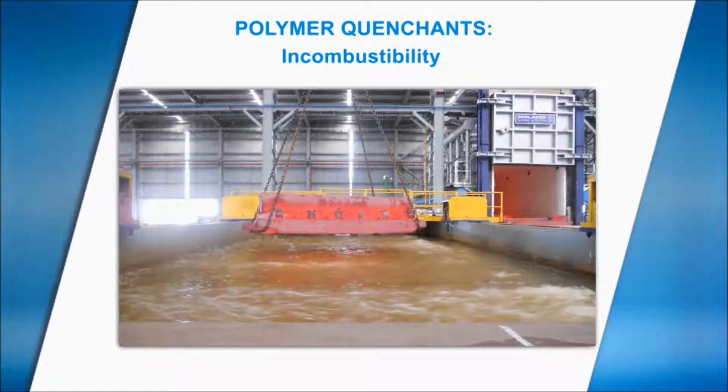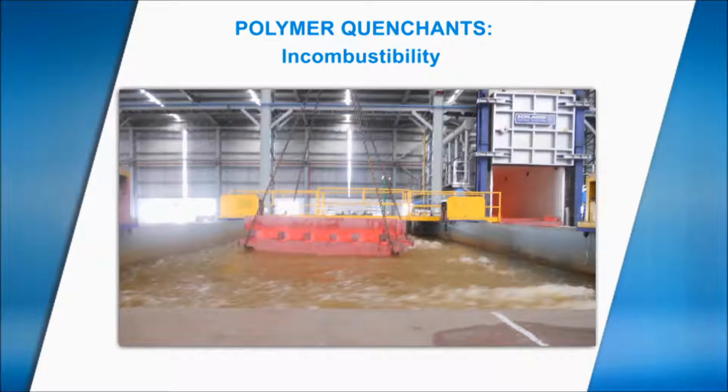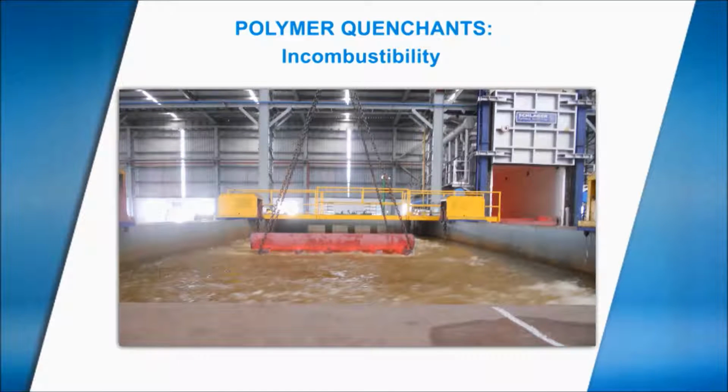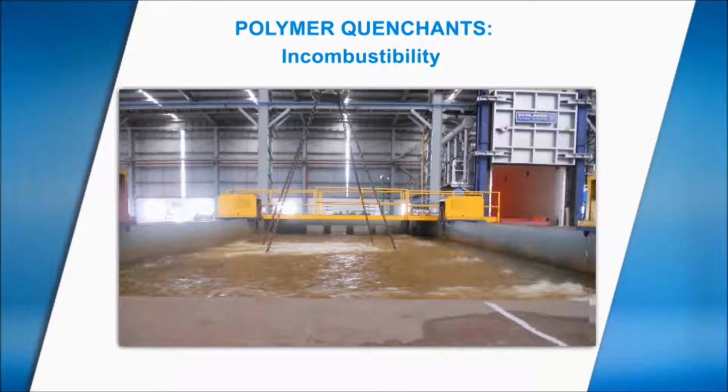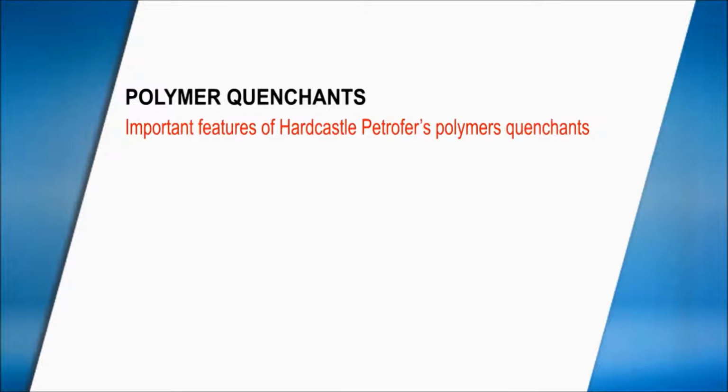All water-miscible quenchants are of course incombustible and, in contrast to oil quenching, help avoid the risk from fume and fire. This is particularly useful when hardening forged parts directly from forging temperature and for interrupted quenching, that is, time quenching of components.